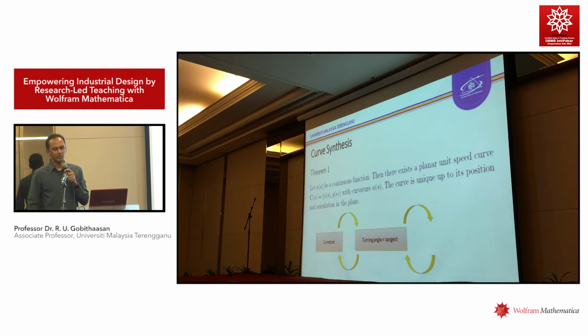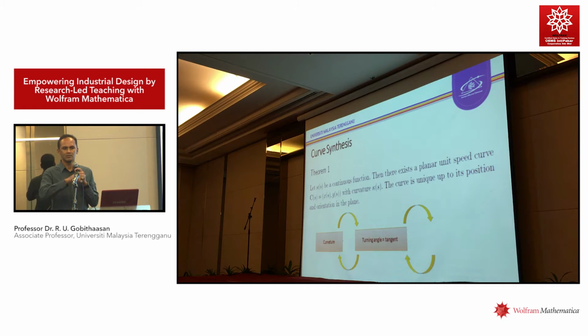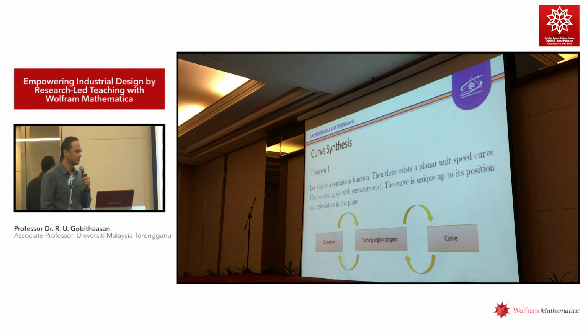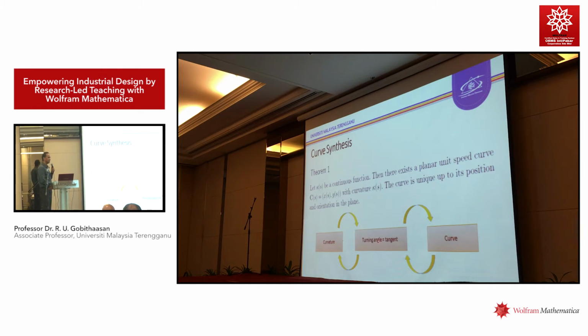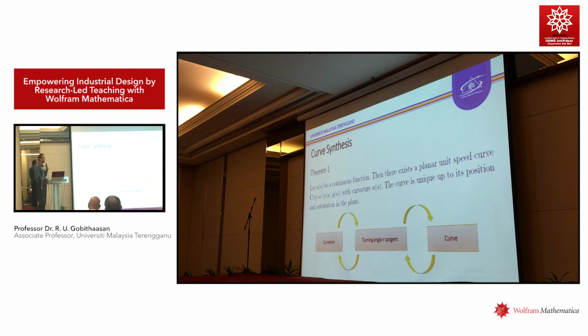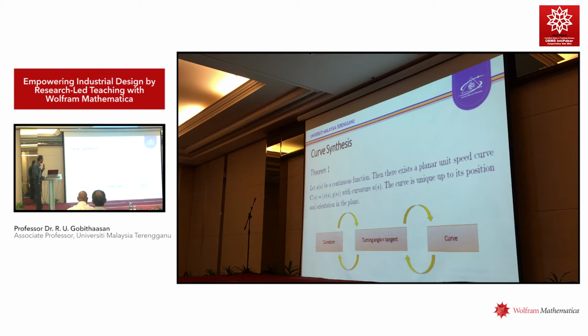Curvature involves the second derivative. So you integrate this, you get the turning angle. Then you integrate the turning angle, you get the curve. For example, just now I showed a Bezier curve. I differentiate the first time, I get its turning angle, or tangent, and then I differentiate again, I would be able to get the curvature.